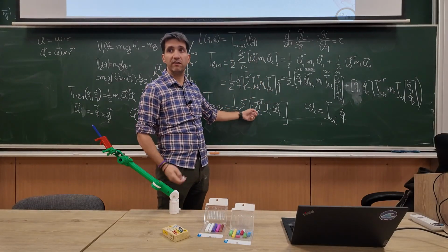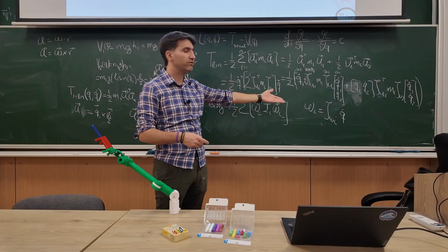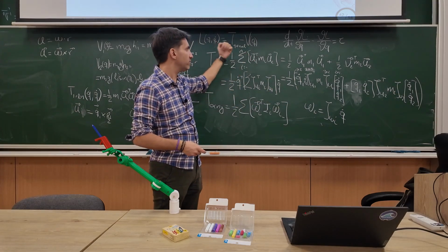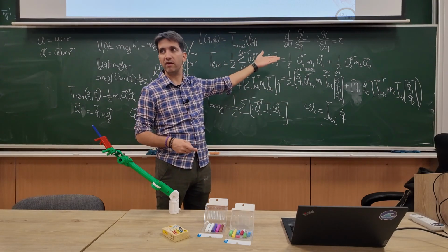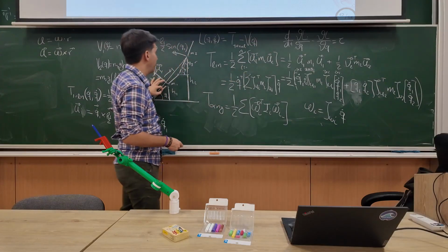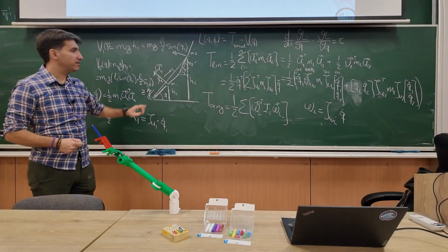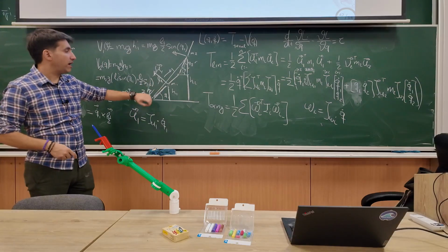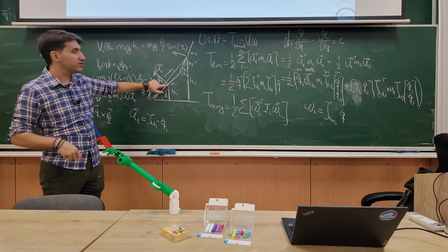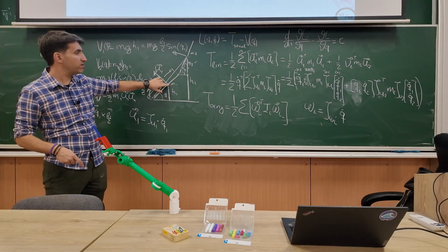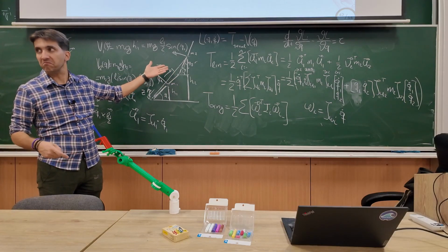I can substitute here. I'm not going again to the same explanation, but it's exactly the same logic. I have linear velocity, I use the linear Jacobian and the masses to calculate it. The same thing for angular velocities, for angular kinetic energy. I use the Jacobian to calculate the angular velocity, right?